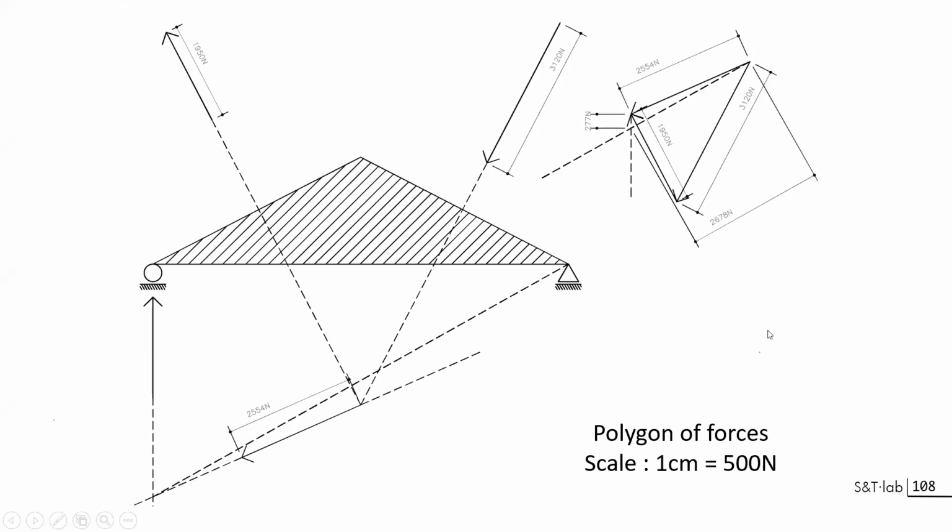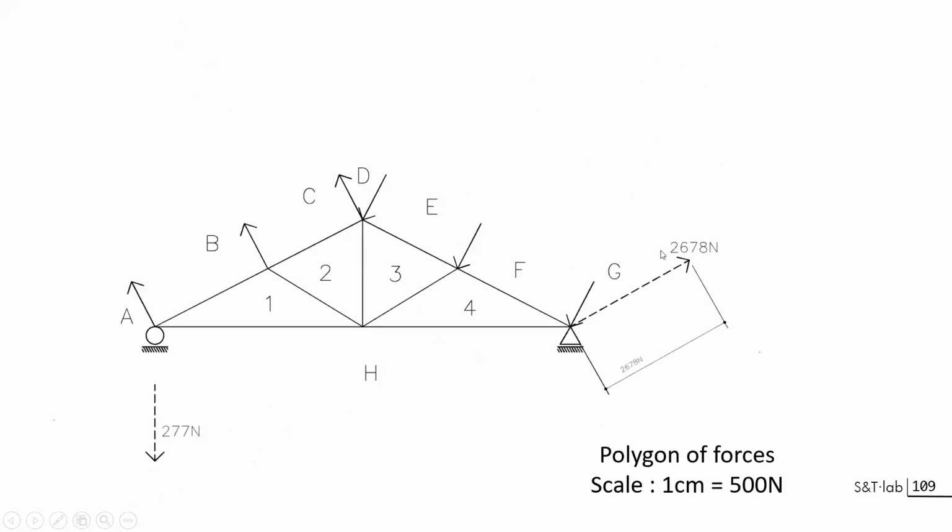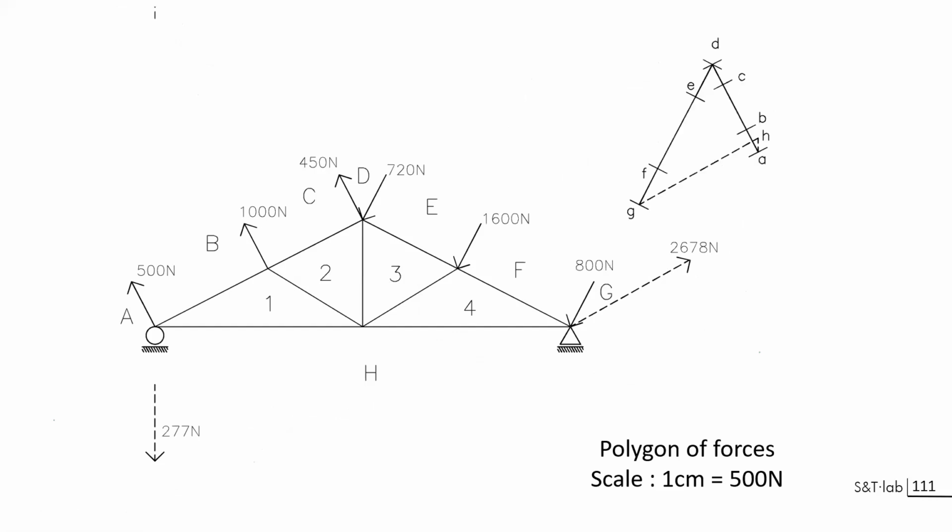I know this vertical, and this intersection here will give you the direction of the forces. So you see the first principles are applied to get the resultant forces. So we know this time what would be the direction of the force on the right, and we can start building the cycle of the line of load. So the load line will be here, it will be broken this time. And this is closed with the reaction forces that are shown here below.